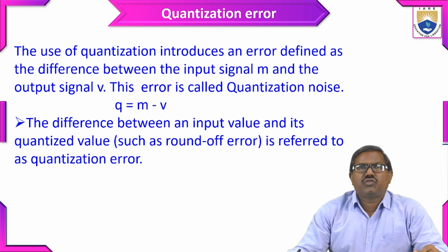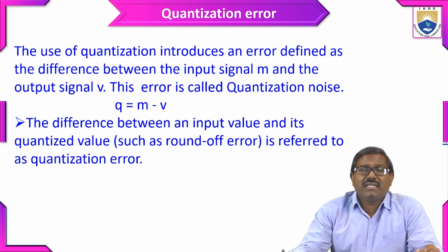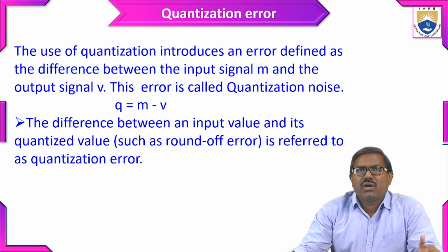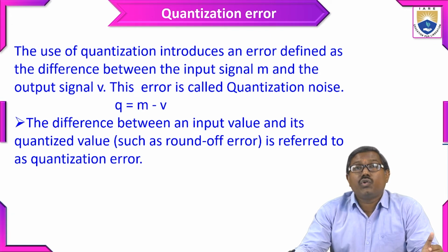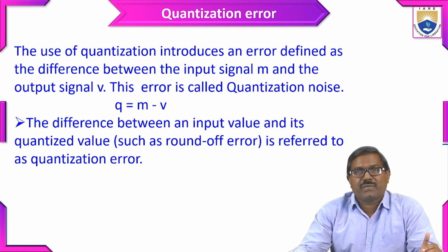So my dear friends, here you can take the quantization error. Earlier we were discussing quantization, which is going to convert continuous amplitude into discrete one. So here some differences we can see. We are going to round off to the nearer predetermined representation levels.